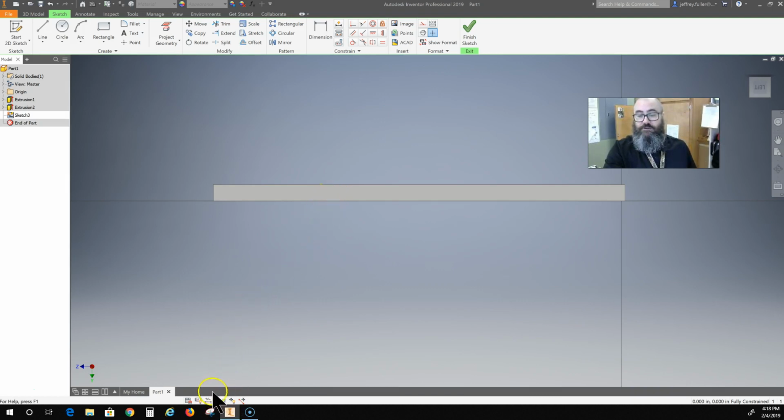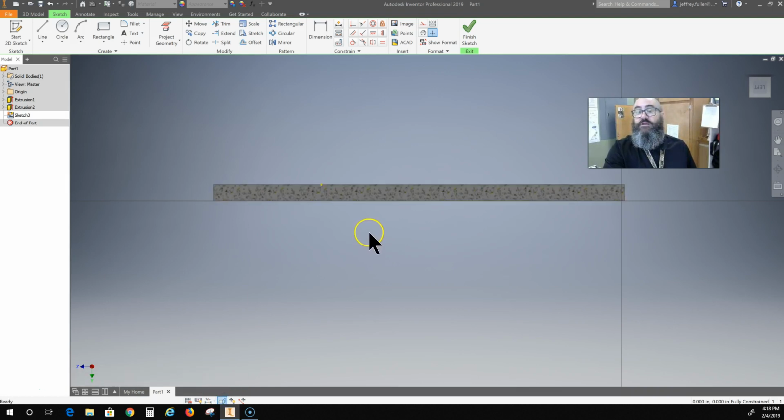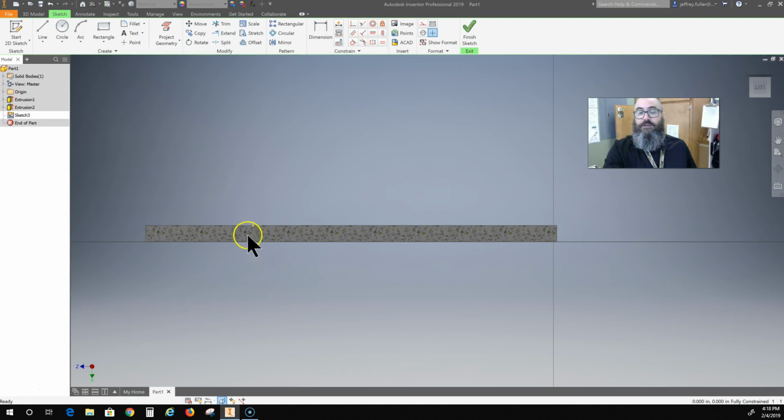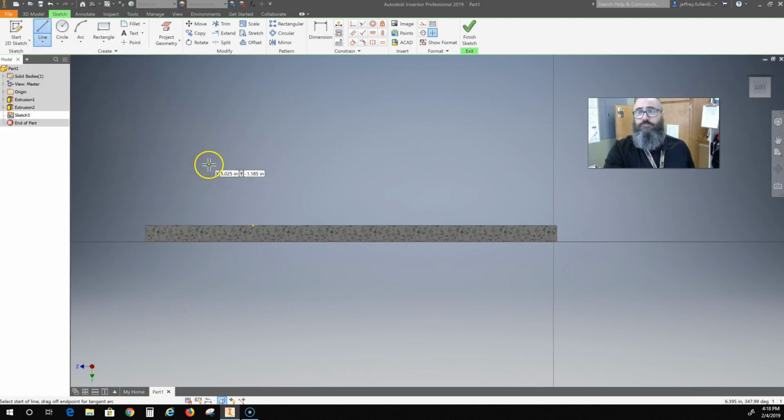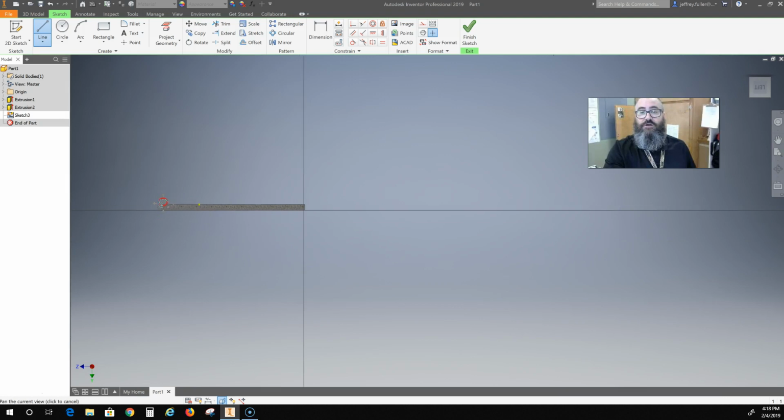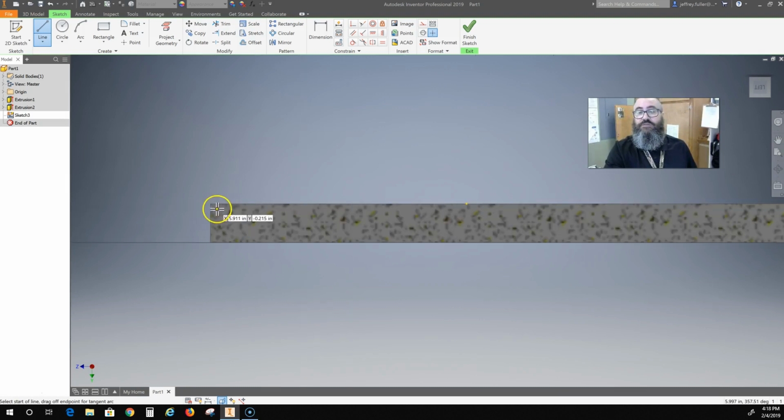So there's a button right down here at the bottom that'll let me cut it in half, and what it's going to do is it's actually going to cut it to the plane that I'm drawing on. So I click that little button right there, and then it cuts it to that plane. Now I can start placing my mullions. And it kind of takes a little playing with at first. I'm just going to draw a single line to start with.